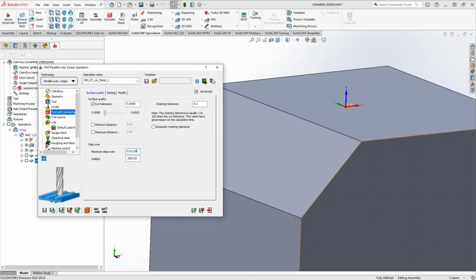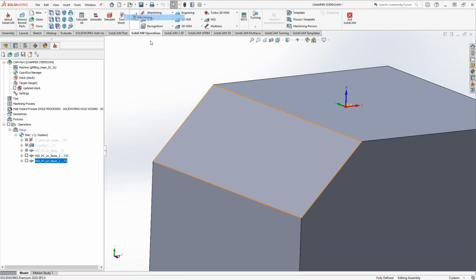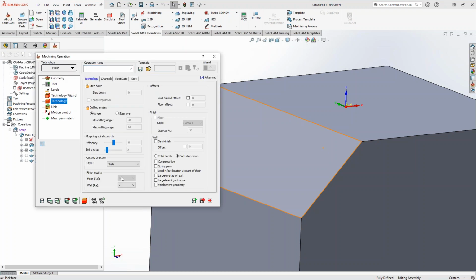A customer will call us up and say, hey, I selected a 32 RA finish, but I'm getting a 48 RA finish when I measure it. Well, like I said, in a perfect world, that's how it is. It's all a mathematical calculation at that point. So what Mark's pulling up right there, the RA finish is all a mathematical calculation, but it's not taking into account machine factors, coolant, run out, all that stuff.